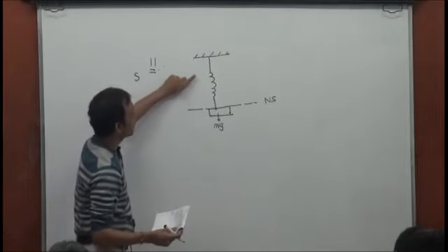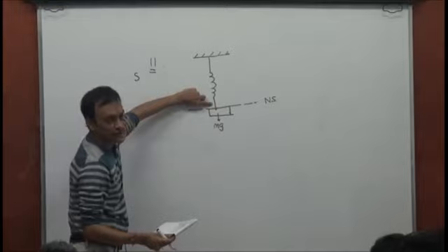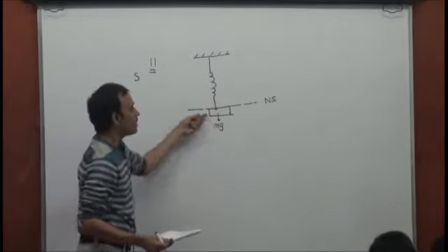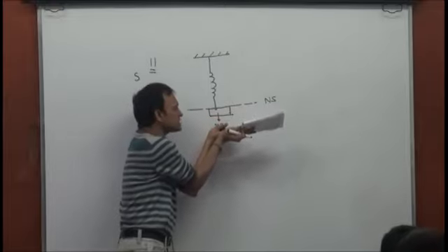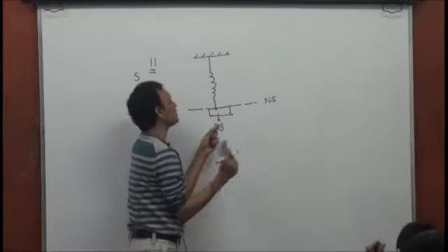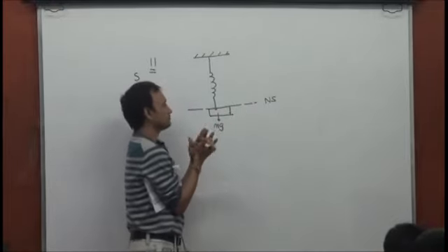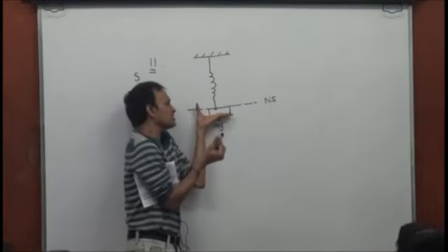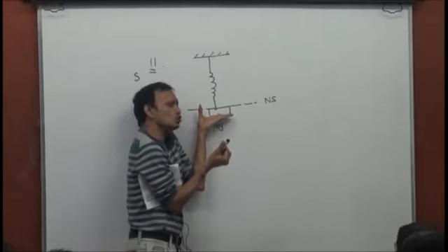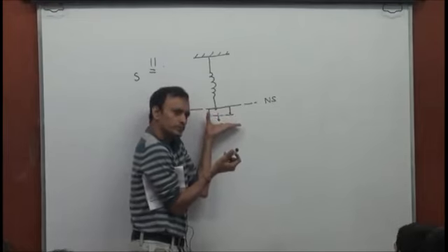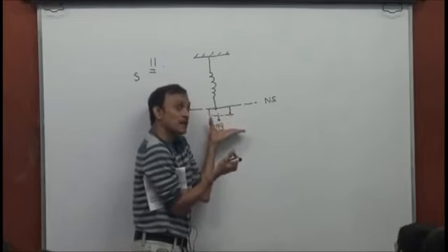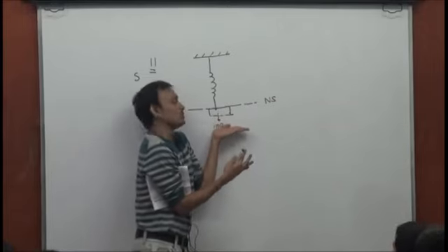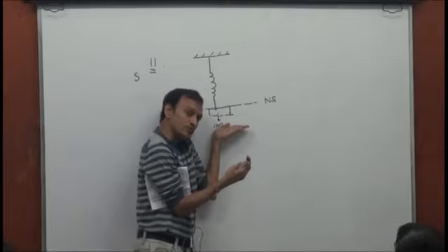Alright, so in problem 11 we have a spring which is originally in its natural state. A mass m is attached to one end and the mass m very slowly moves to an equilibrium position. That means what's done is, this mass is held here at this point and this palm is slowly lowered. That means the spring does extend, but the mass never gathers velocity because the palm is preventing it from gathering velocity.